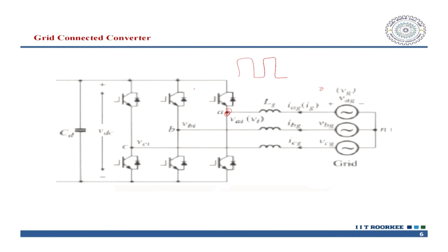So, this is the way we require to control the grid connected inverter, and it may act as an active rectifier sometimes, because you may have a bulk of batteries to be charged in a sinusoidal fashion. And the reverse can also be true, because you may have peak management control, especially in the evening. So, you want to feed the power from the storage element, or you may have a solar, then power will flow back from the DC side to the AC side.